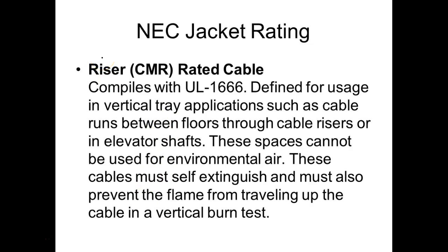Riser, these are cables basically that would be hard-drawn wires, but they give us the ability to run them up without suspending them, and these have length limits too. We'll look at those, I think in one of our next slides, where we can see the actual length we can run a riser rated cable without supporting it with some type of clamp.